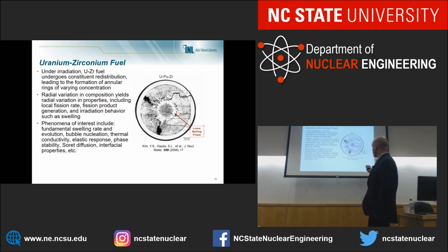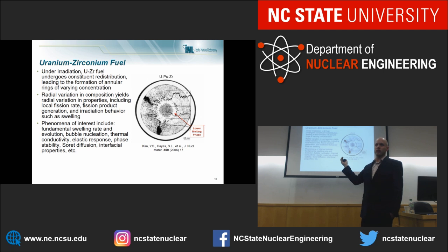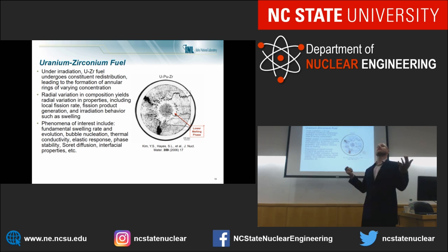So we're getting zirconium to diffuse up the temperature gradient as the system is evolving. And so we're getting zirconium enriched, which has a higher melting point. We're getting zirconium depleted systems, which have a lower melting point in these systems. And of course, if you're changing the composition of these phases that you're dealing with, you're getting different thermal properties, different elastic properties, different defect properties that are changing as we change in R. And we're getting different phases as we change too.